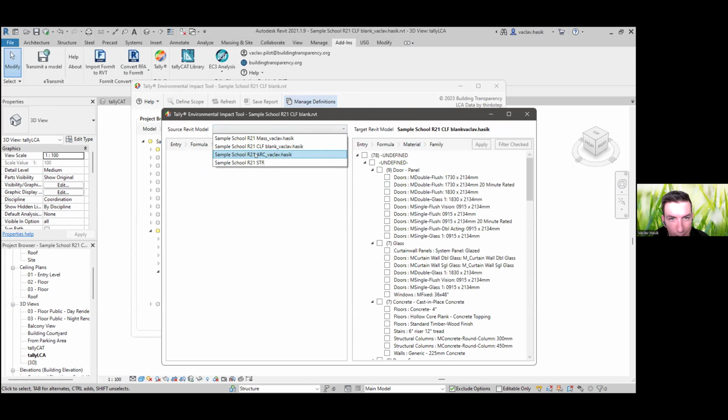So the way that it's showing you the embodied carbon emissions here, 3910, that's the total over time, including any of the replacements, etc., over the period of the lifetime of the building, which EPiC, I think, currently is assuming 50 years. Normally in whole building LCA tools, the lifetime is typically 60 years. I believe EPiC actually uses a 50-year lifetime, but I know they were making some updates to make it more flexible recently.